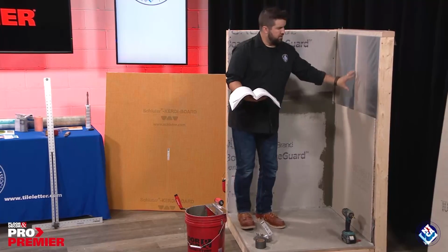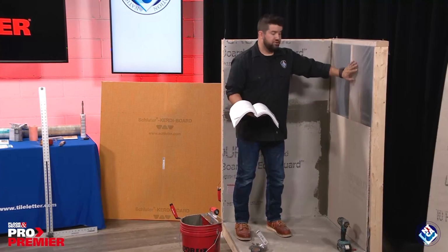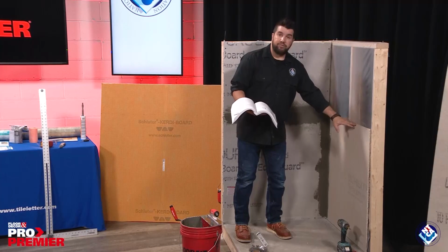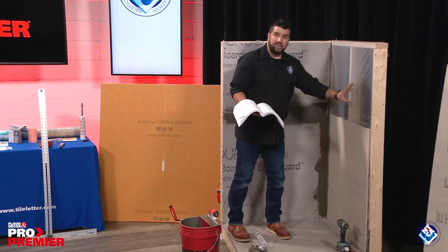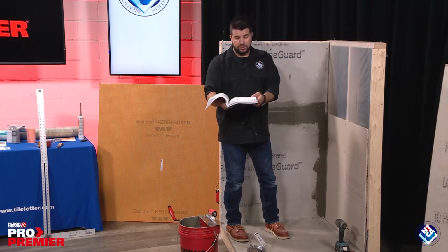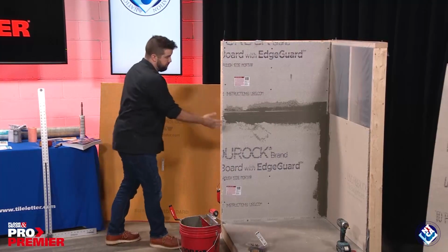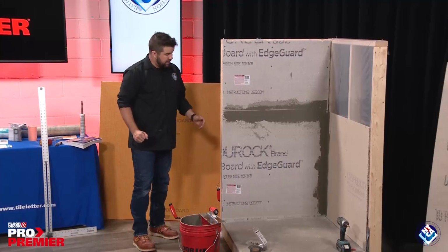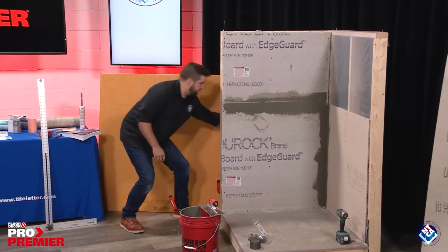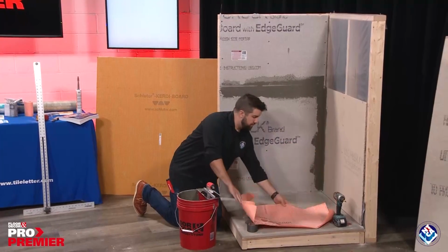So I left this board off so that you could see I've got this vapor retarder right here, and this is just a 6 mil plastic, but this is behind our fiber cement board. So that's one option, and that would fall under one of the classifications of the environmental exposure. Another option would be to put a membrane on this wall. And we're going to go ahead and do that now. And so this is the membrane right here that we're going to use. And so let's get started on that.